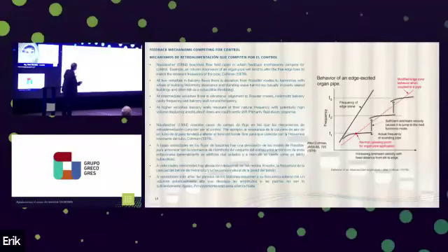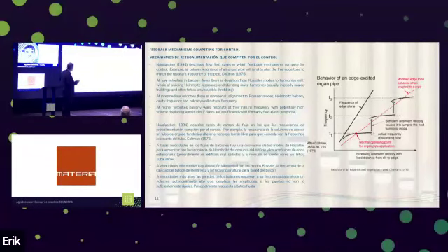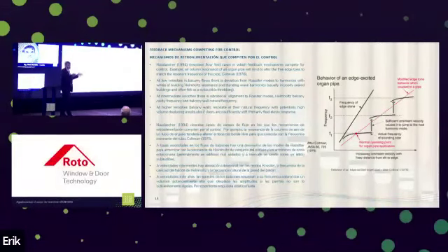Now, Nadosha describes flow field cases in which mechanisms compete for control. Examples are air column resonance of an organ pipe, which will alter the free edge tone to match the resonant frequency of the pipe. It's like the Rossiter dynamic excitation competing with the resonant excitation. This is what happens in woodwind instruments, for example.